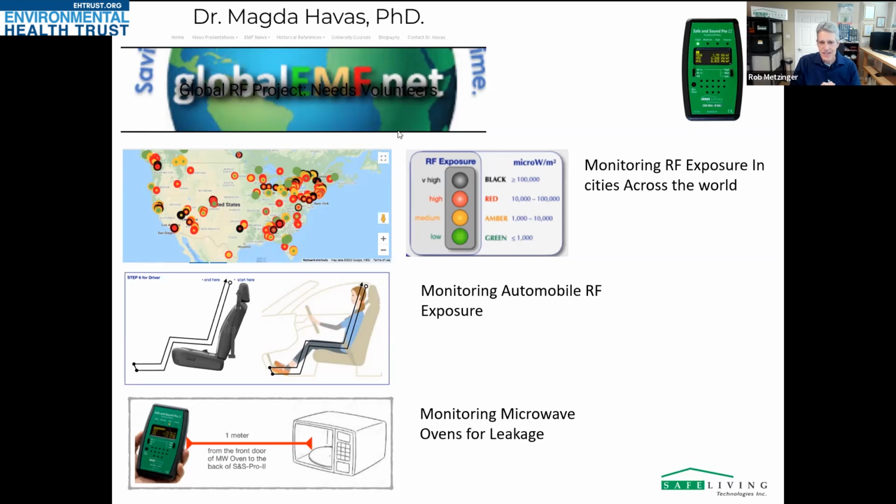Well, in industry, if we're doing official measurements for government or legal entities, typically it's a 2-year period. You need to get a calibration certificate every 2 years. If it's just a home use meter, something like this, I don't think you need to worry about it. If you notice extraneous readings or readings that just don't make sense, then maybe we should get it in here and do a calibration, or even compare it to a meter off the shelf, just to make sure it compares the same.